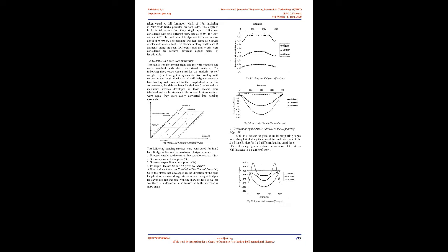The slab was meshed with element size of 500 x 500 mm. The number of solid elements across depth is 8 layered. The results found out are given below. The major bending stress along the span comes out to be 2.072 N/mm2, the shear stress along the supports comes out to be 1.66 N/mm2. As seen from the graph below, nearly all the elements are giving the same results. However, the shear stress is found to be highly distorted for elements other than SOLID 73.